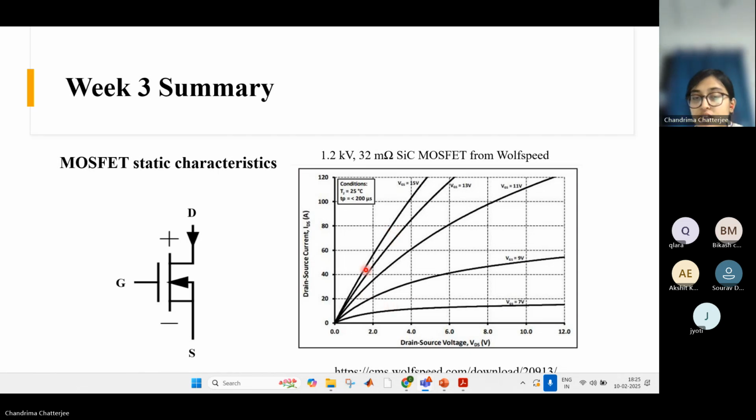So yeah, here in the y-axis we have the drain current, and in the x-axis we have VDS. So the slope, delta y by delta x, will be current by voltage. If you get the reciprocal of that, you will get the RDS on, the resistance of the MOSFET during turn on condition. And like BJT, in BJT we had the control parameter which was the base current.